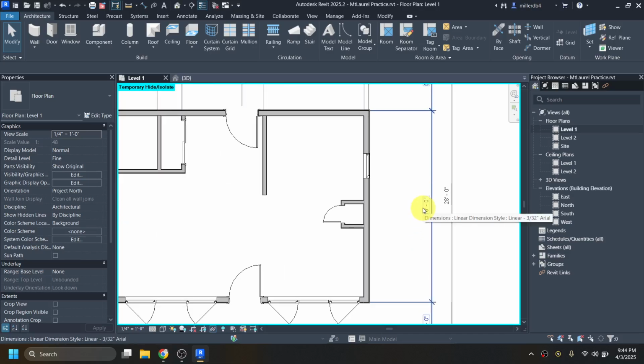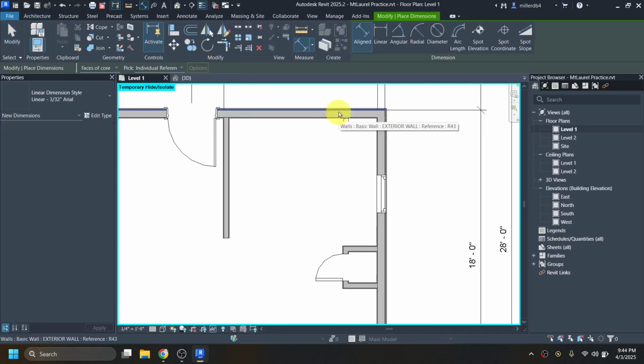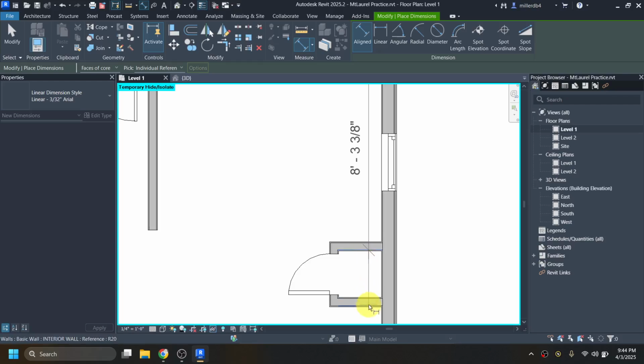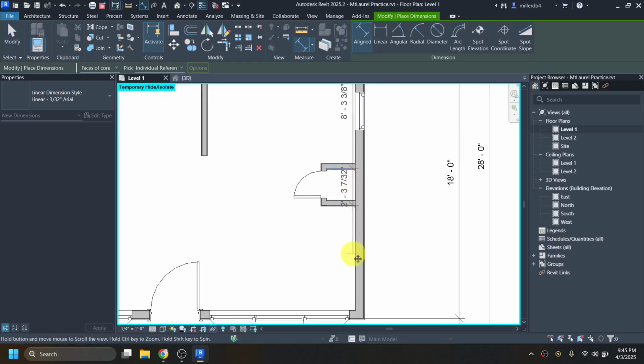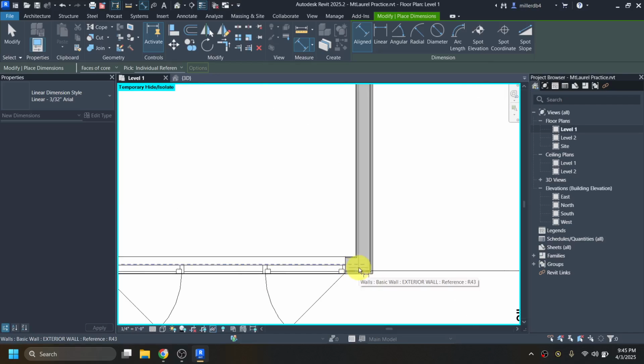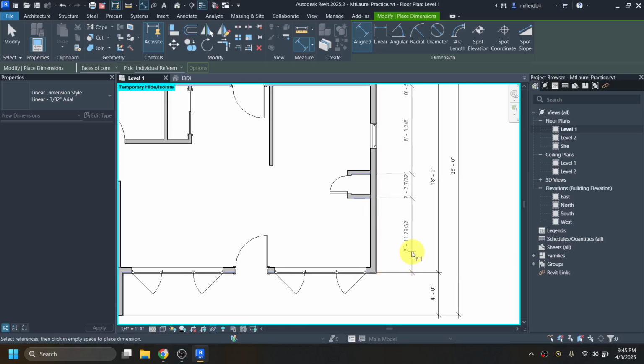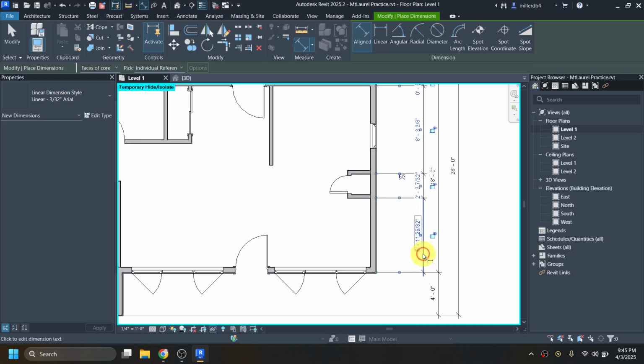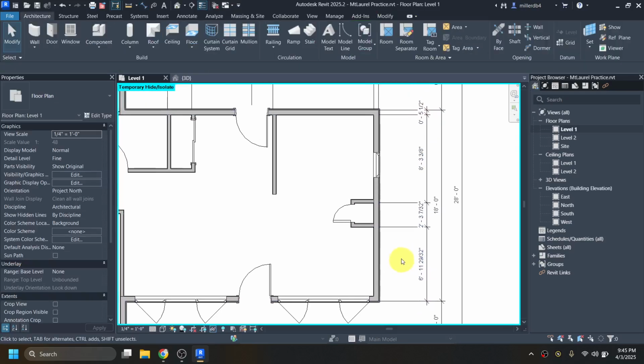And then I'll measure to the centers of the faces of my walls installed on this one. So again, keyword shortcut DI. I'm going to go from face to face to face, face. Make sure that this one's going to this one's face. Okay. Click to place, escape 100 times.